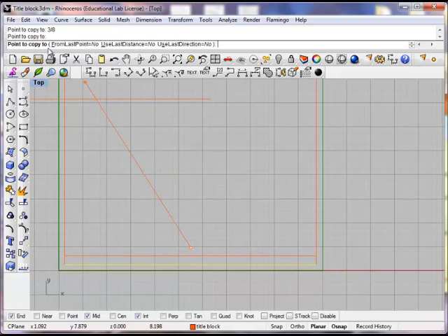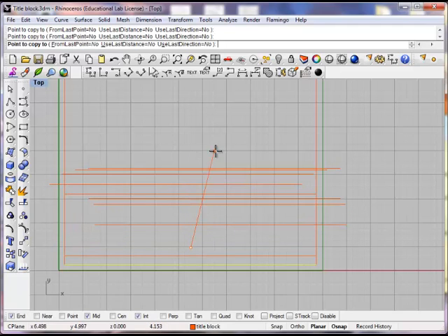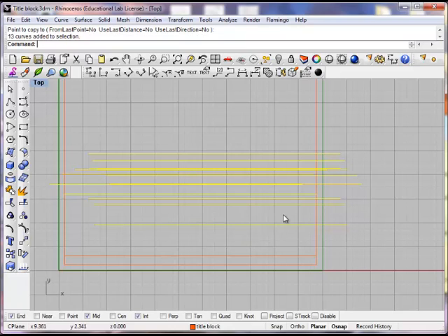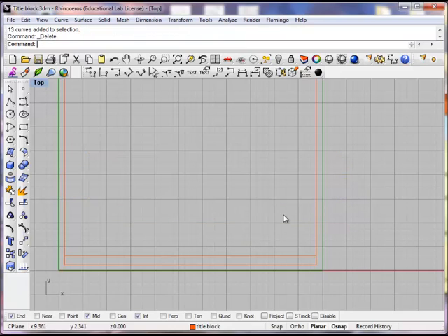Now we can continue if I wanted to keep selecting things and picking points. So I've just copied a whole bunch of lines that I don't really need. I can hit escape, or enter. This is going to get me out of the command. I'll get rid of these. You hopefully don't have those, and then I can just select it, hit my delete button, and they're gone.